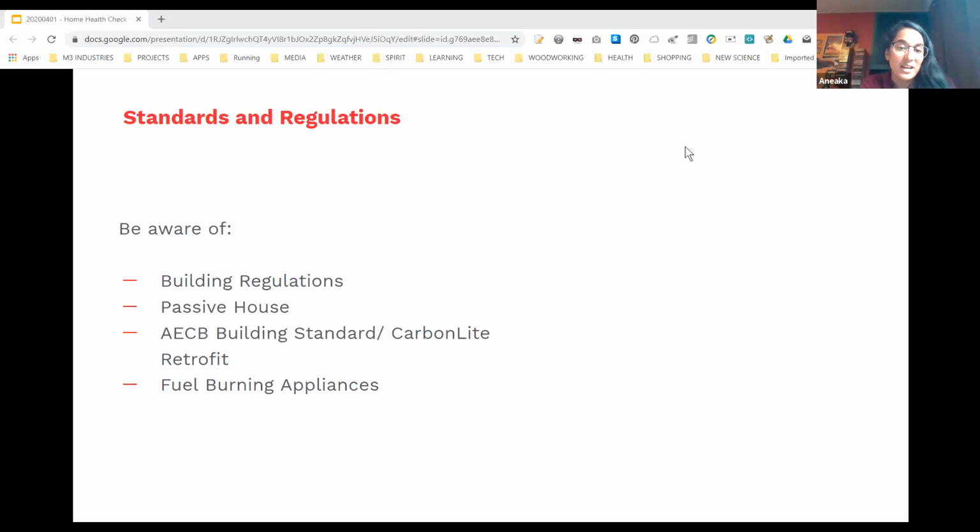But you're right, because actually by opening your window, you're cooling down that room, particularly if it's cold outside. And if you're cooling down that room, that means the dew point will change. So if you think colder air has a lower holding capacity for water, you're more likely to get mold growth in a cold space than you will in a warmer space. So it isn't the best idea if you have the option to have a ventilation system that works. It's definitely better to have a ventilation system. Obviously, if it's your only choice, it's kind of what you have to do.